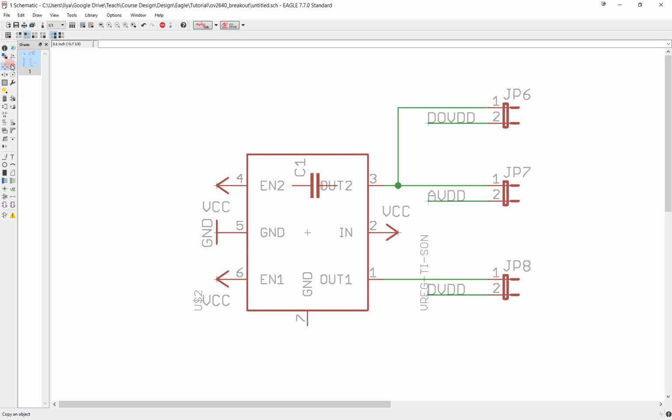So I'm going to do this, and it needs 3 capacitors. One here and another here. And so then once again I have to connect to the same thing right here. So this needs one between this output and ground. So then I'll place this over here and to ground. And it needs a capacitor between the second output and also ground, and also between the input power supply and ground. So now it's all connected with 3 capacitors.